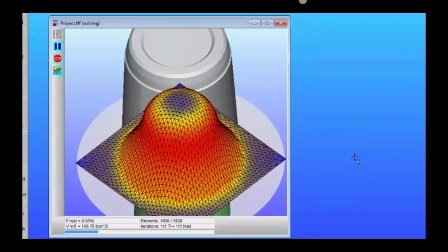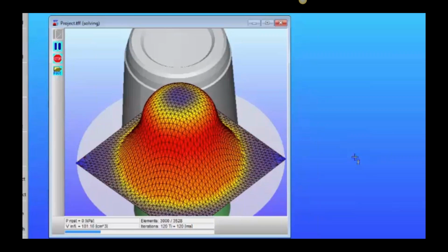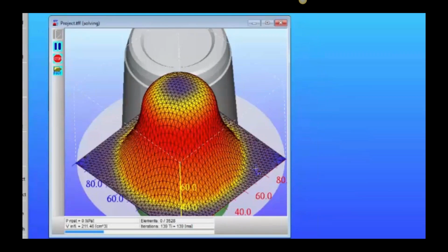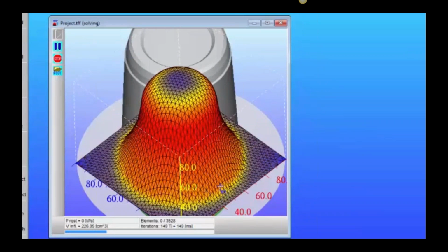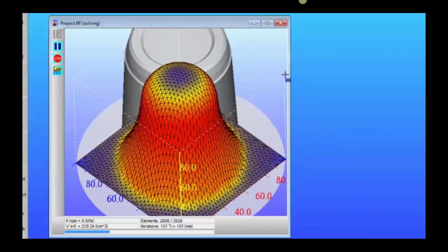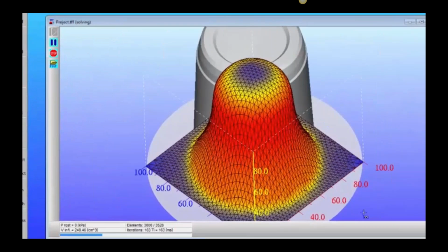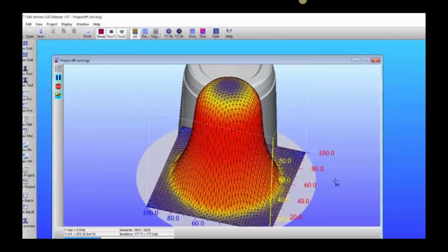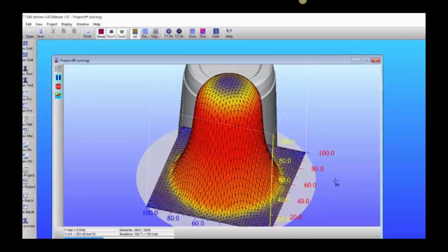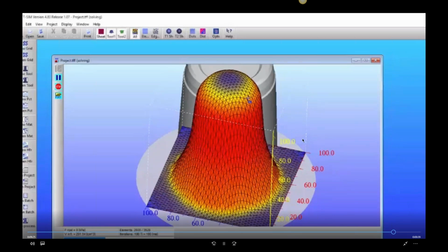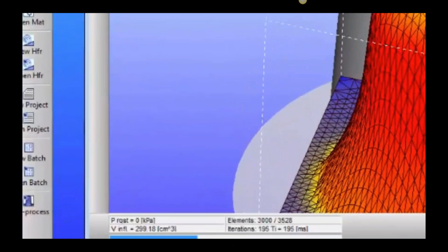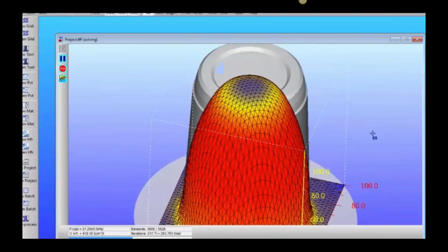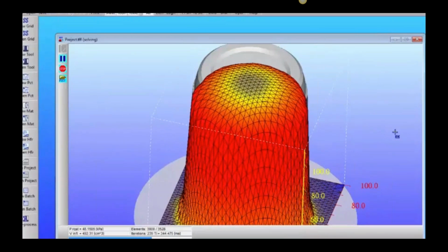Once you finish the simulation, you can also export your formed or deformed mesh, the final part shape, out for structural analysis and study the deformation or crushing test, let's say in ANSYS or Abaqus or some other finite element stress analysis program. Here we're showing the bounding box that kind of shows the size of the sheet. And here you can see at 200 milliseconds, now the vacuum comes on and completes the forming.